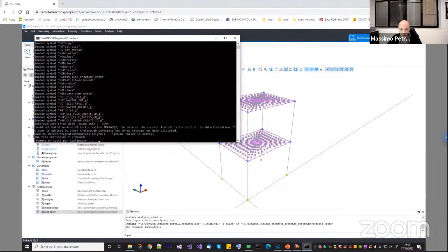Okay. Now, in this case, we have 8 eigenvalues. The problem is that the ARPACK solver, which is very optimized for sparse matrices and so on, has a limitation. You cannot ask for all the eigenvalues. At most, you can ask for n minus 1 eigenvalues, where n is the maximum number of eigenvalues available. So this is the only case in which the ARPACK solver may fail.